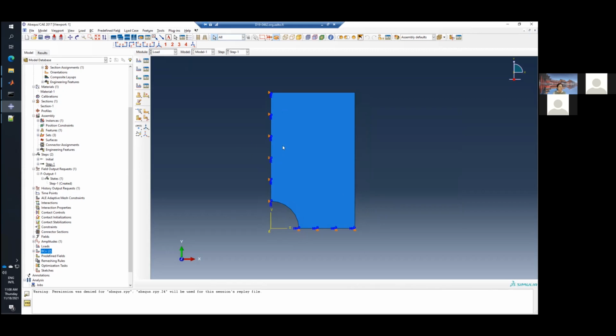So these are the first two boundary conditions. This will define the model as a symmetry model, so you see with this one, you will finally generate only a quarter of a 2D model. And then we need to add a final boundary condition to control your loading.